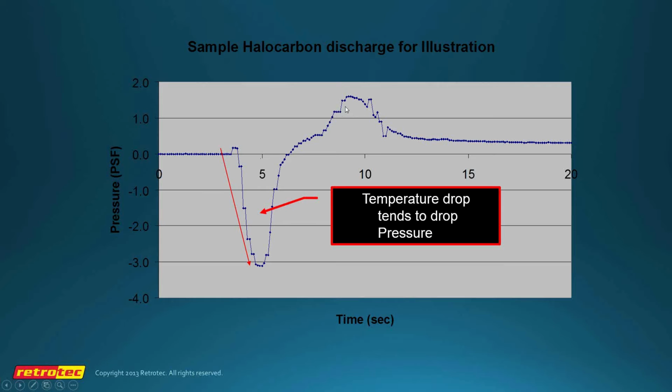What that means, of course, is that most of the vents in Europe that have been installed for halocarbons have actually been installed backwards. So it's important to do this evaluation and to be installing vents that will relieve the pressure in the direction that the pressure is going to occur in. And there are dual acting vents that will do that, that will open in both directions.